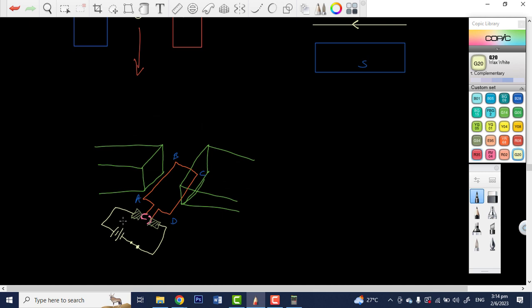So what we'll see now is that we're going to have a current flowing. When the switch is closed, or when the circuit is activated, we're going to consider conventional current, which involves the movement of positive charges. So we're going to have current flowing from this end through the carbon brush, through the split ring, and then through the loop. So current goes in on that side, and then naturally current is going to come out on this side. Now remember that we have to have our magnetic field lines. They're going to be going from north to south like that.